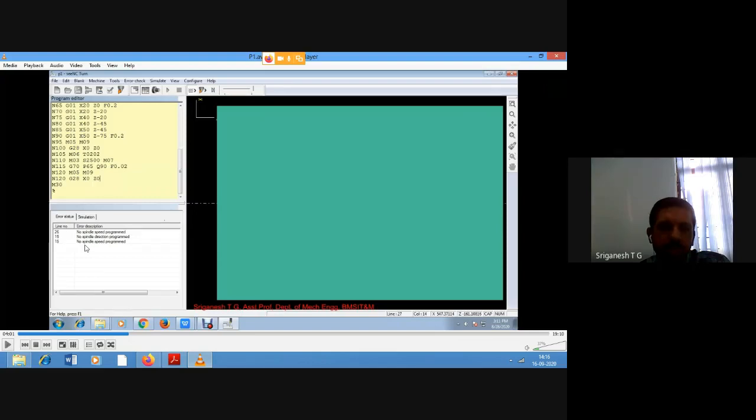Now see here in the dialog box, you can see 3 errors that are being listed. Line number 26, end spindle speed programmed, okay. Then line number 15, end spindle direction programmed. So there are errors if it is not aligned properly. I mean alignment means it should come in a proper sequence. So always after the usage of the tool, it should be moved back to its home position, and after that the next step should be spindle off, okay.